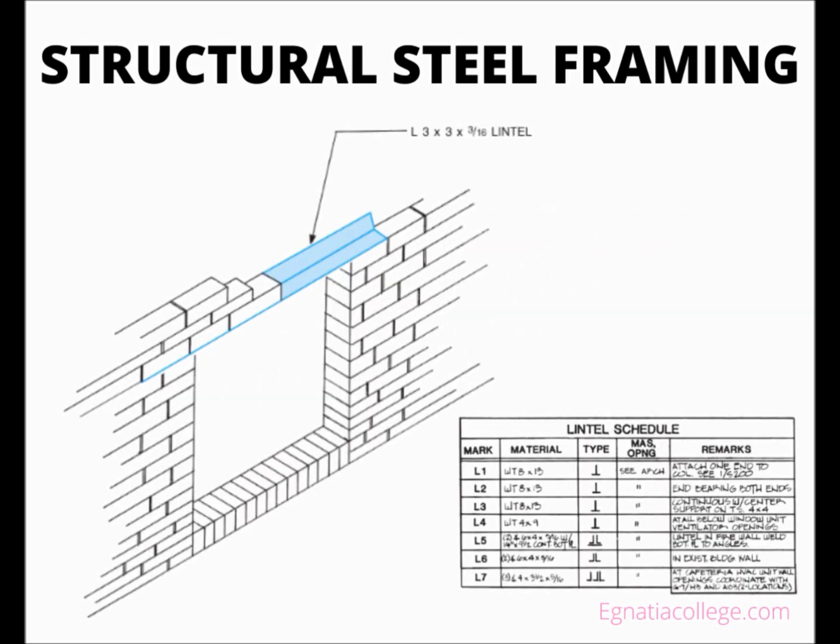The actual lengths of members are not shown on the general contract drawings. This information is shown on shop drawings that are drawn by the steel fabricator some time after the construction drawings are completed. It is an easy matter, however, to find the span of the member by looking at the framing plan. Connections are shown on details and sections.